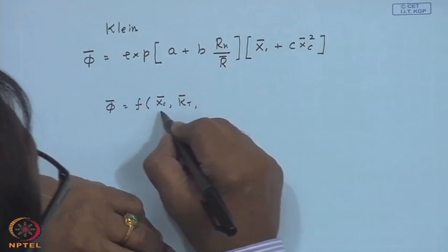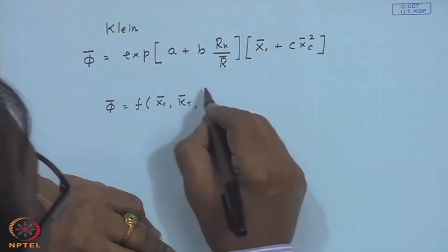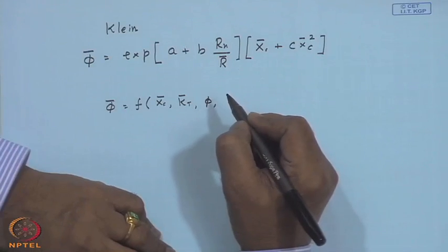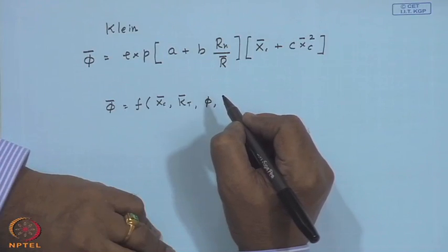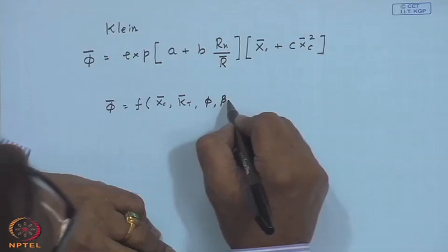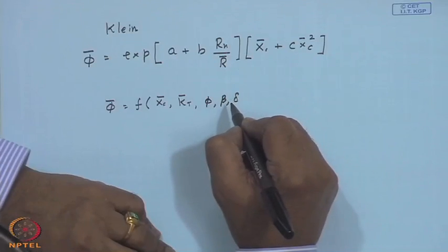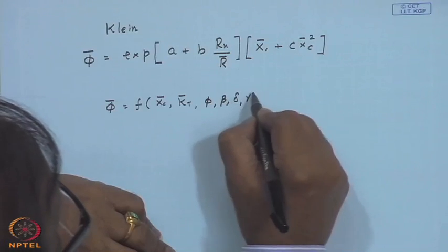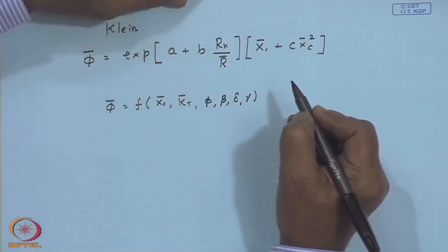And X t bar, K T bar, and the latitude, because it will definitely have some effect on the noontime radiation compared to horizontal radiation, or the tilted radiation compared to the horizontal radiation. The slope, the declination delta, the month, because this R B R factor strongly depends upon this, and of course, gamma if it is non-surface-facing-south.